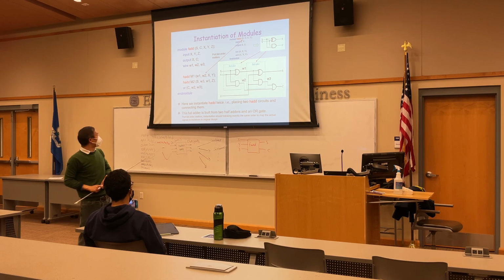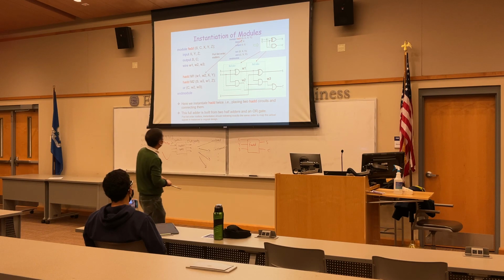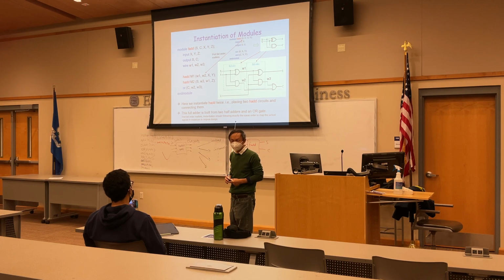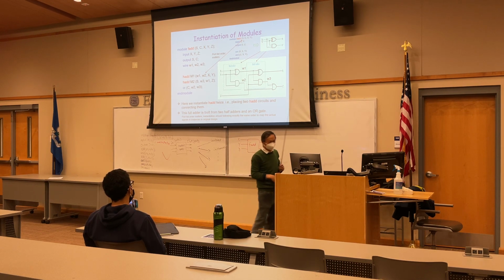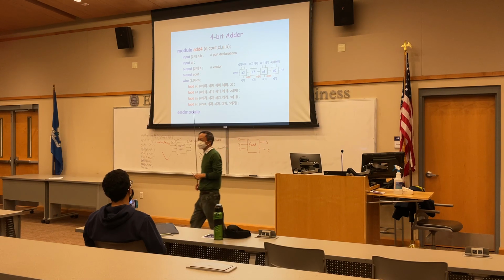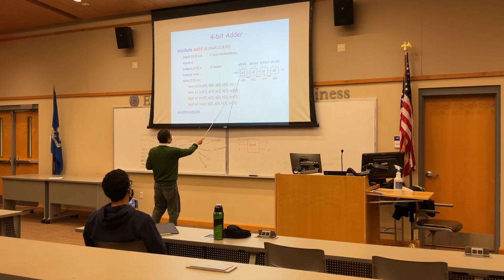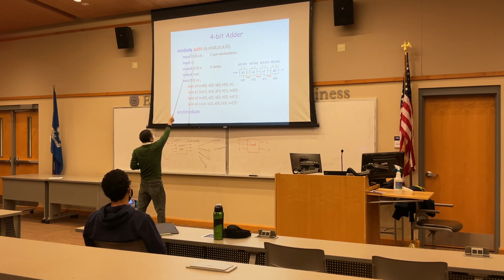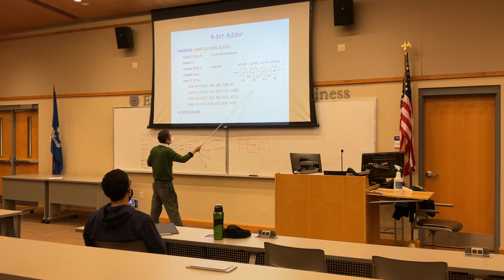Can you design a what? This is a 1-bit full adder, right? Can you use this 1-bit full adder to design a 4-bit full adder? See? We can also challenge you. Example. Okay? 4-bit full adder. We already designed a 1-bit full adder. Now, can you cascade them together? Then you need to call 4 instances. And again, give a name. And this is the total in and out, the port list. Each of them specified.